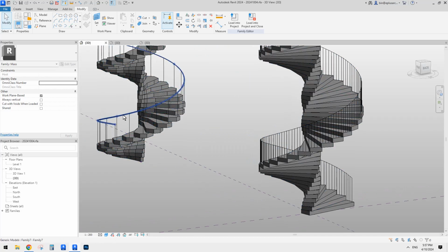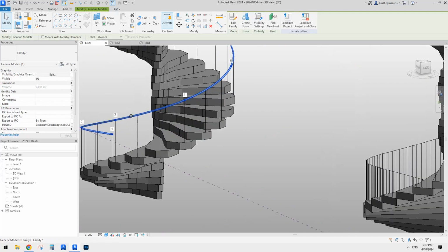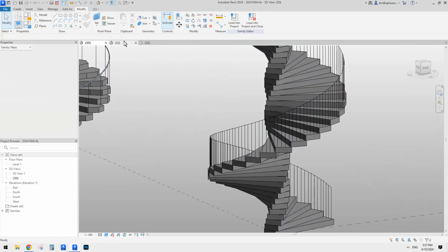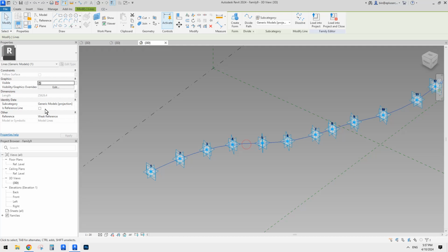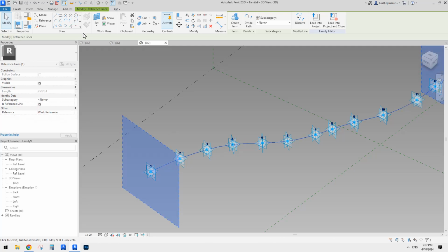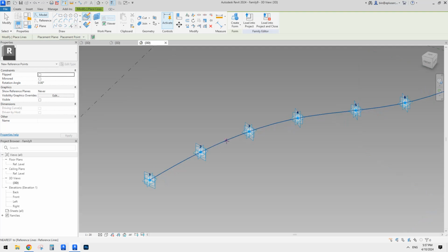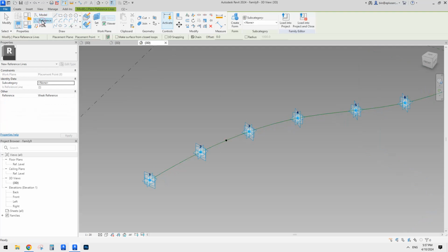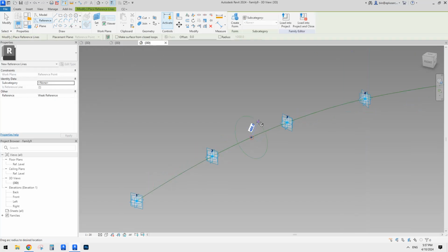Now let's do the final step. Can we just do a railing with a diameter? Yeah, that's very simple. Just go back again here. This time we're going to change this one to a reference line and then place a point, use draw on face. Place onto this, and then circle reference, circle, draw on work plane, set work plane, pick this work plane on this point, create a circle.